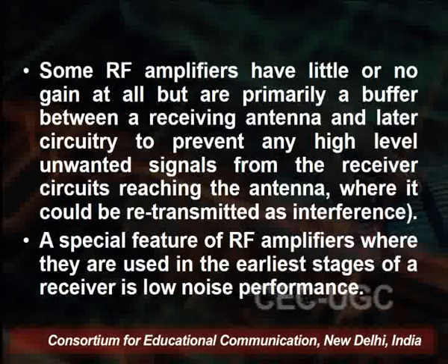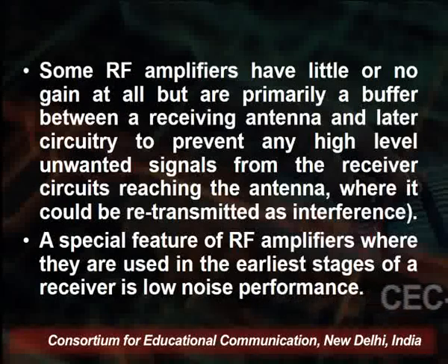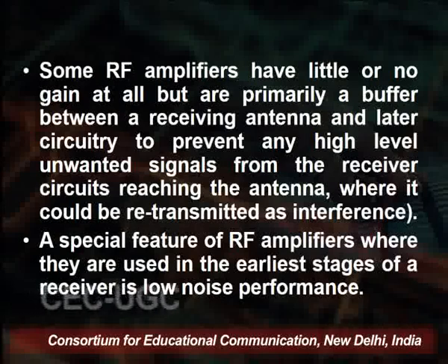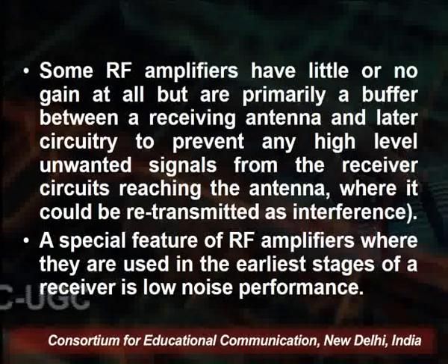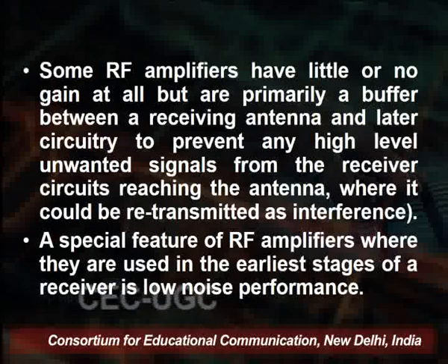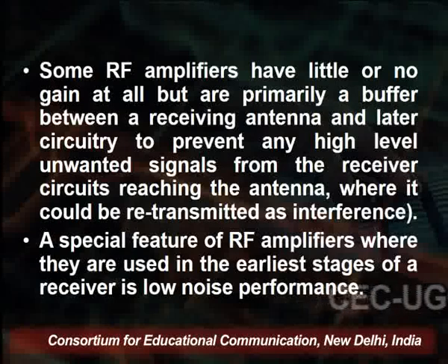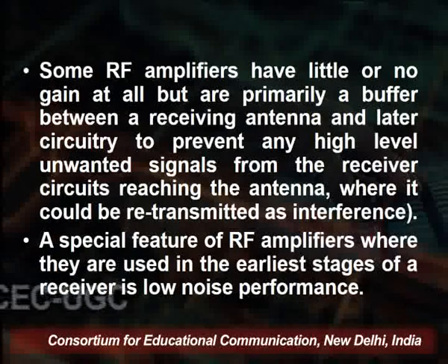Now the RF amplifiers have little or no gain at all, but are primarily a buffer between the receiving antenna and the later circuitry, to prevent a high level of unwanted signal from the receiver circuit reaching the antenna, where it could be retransmitted as interference. So this RF amplifier has no gain.